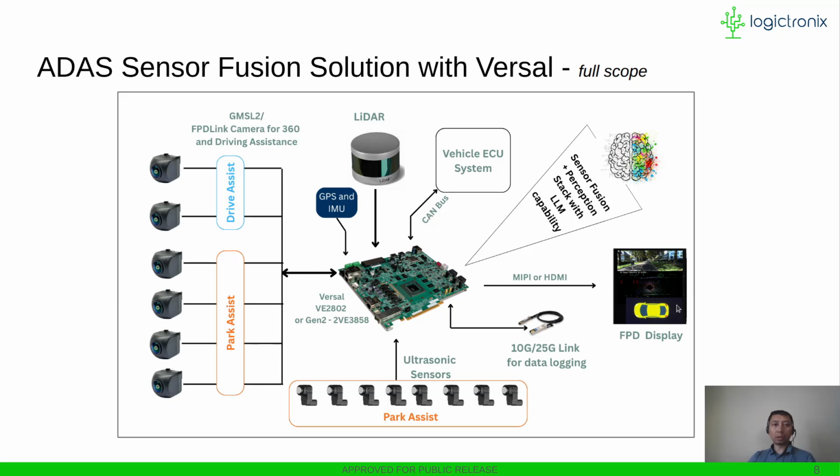Here is the hardware architecture for the ADAS sensor fusion solution, which we developed at Logictronics. For the processing part, we are using the Versal VEK280 platform. For the sensor input part, we are using GMSL cameras and ultrasonic sensors for park assistance and driver assistance related applications.